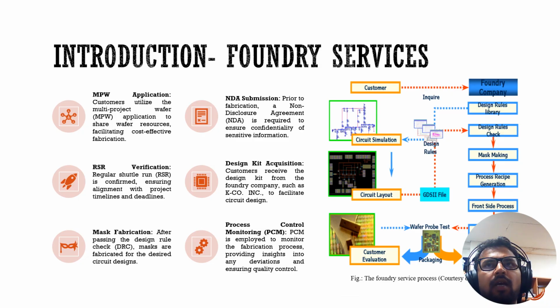Moving forward, we have the introduction to foundry services, where you can see the whole foundry service represented in the figure. There are multiple processes, which include MPW, which refers to multi-project wafer application, which shares wafer resources, facilitating cost-effective fabrication. NDA refers to the non-disclosure agreement, which is required to ensure confidentiality of sensitive information, whereas RSR refers to regular shuttle run, which is confirmed, ensuring alignment with the project timeline.